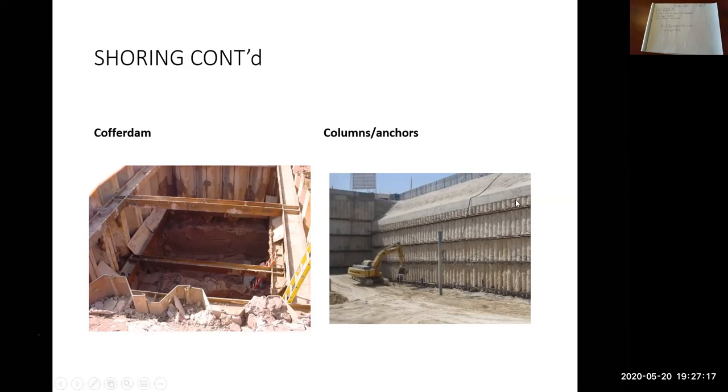So another type of shoring system. Columns have been driven in here, again with anchors, so anchors going into the slope. Again, it's another method to have a vertical excavated face, so that you don't have to slope it one-to-one, taking up increased room.